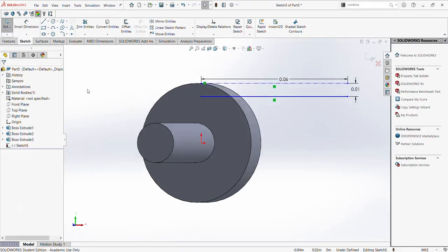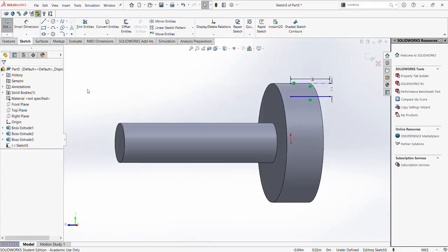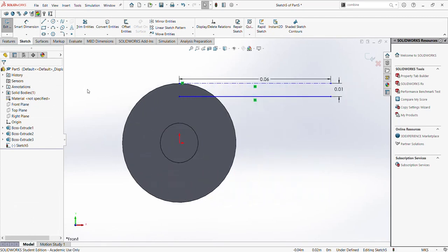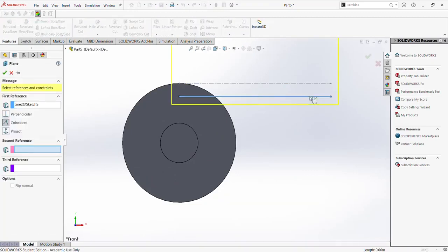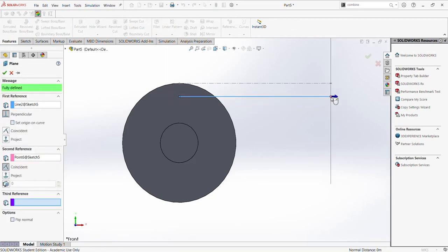And then now you want to put a circle here, but you have to make an extra plane. So for that, you're gonna go back and go to the features, and then you're gonna go to reference, and then insert a plane. You gotta pick up this line and then this edge, so face to the right side of where you want to put your outlet circle, or how you want to make your pump look like from the side. So you pick that up.